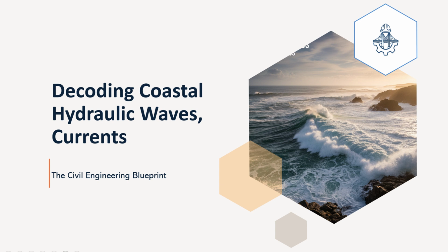There are two primary modes we focus on. First is longshore transport, also widely known as littoral drift. As we discussed, this is the movement of sediment parallel to the coastline, primarily driven by those longshore currents generated by waves breaking at an angle. It results in the gradual shifting and redistribution of entire beaches, eroding sand from updrift areas and depositing it further down the coast in the downdrift direction.